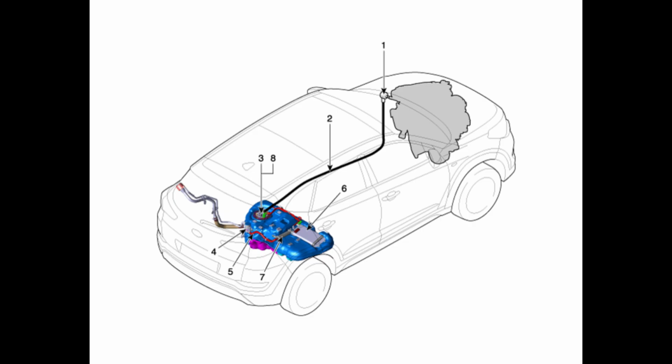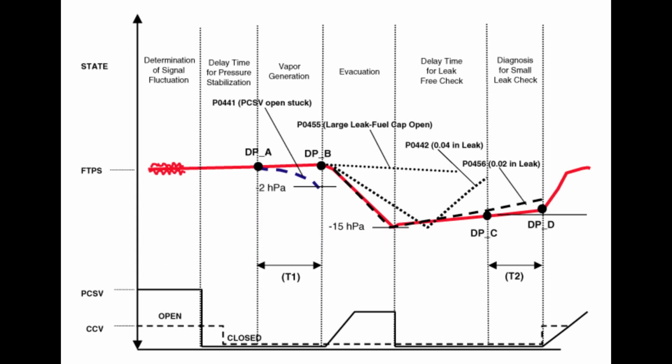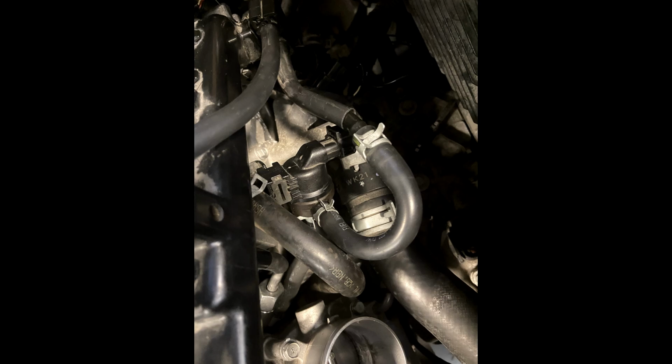Fuel vapor in the tank is then forced to flow into the canister via the fill vent valve. The liquid vapor separator isolates the liquid fuel and passes pure vapor to the charcoal canister. When the engine is operating, trapped vapor in the canister is drawn and emptied back into the intake manifold for the engine to use. This occurs during the purging process and recovers the canister's absorbing capacity.